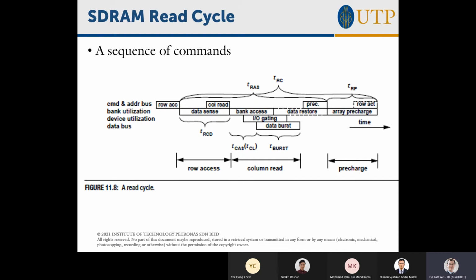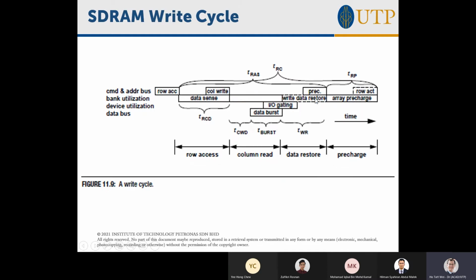Okay, you have to implement a circuit that can talk to the SDRAM chip, which literally means you issue a row access command, a column read command, and a pre-charge command respecting all this timing. You also need to do a write cycle, which is basically nothing else but a row access command, a column write command, and a pre-charge command. So you notice the pre-charge command always comes after the write cycle, right? As you see, when you write, you actually don't need to pre-charge, right?